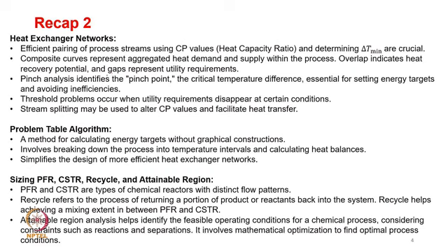And then in that direction we learned about composite curves. We also learned about pinch analysis and the pinch point. The pinch point is the critical temperature difference. It is essential for setting the energy target to avoid inefficiencies.